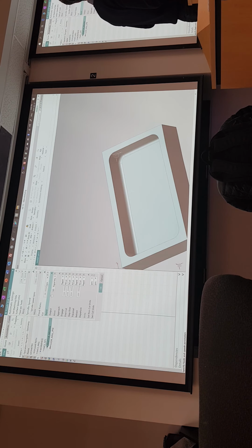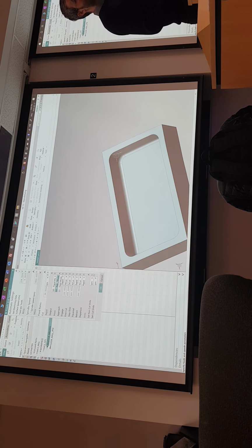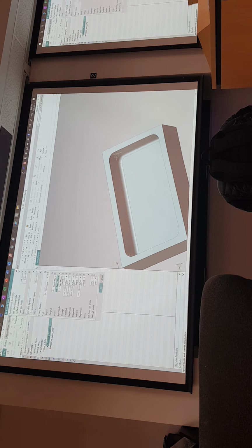And then, like I mentioned before, you can set different, for example, rapid. You tell the machine to rapid at G0, which is the rapid mode of the machine. Maybe you want every rapid move to feed. I don't know why, but there are some unique instances where you want to do that. Let's say you're in a corner and you're slicing that corner, and you have lots of little tool paths. Maybe you don't want to come down, slice, come up, wrap it over, come down, slice, come up.